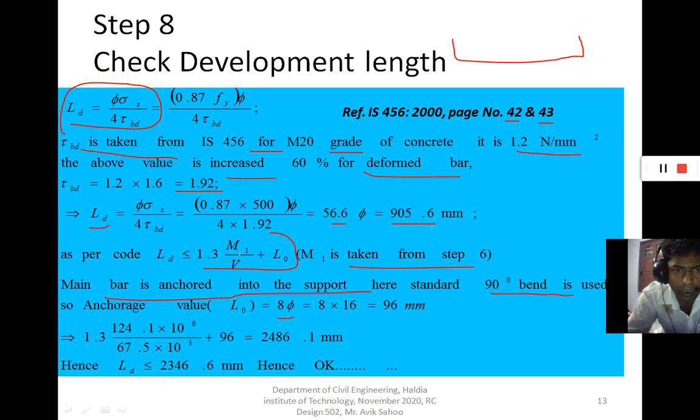And here the M1, approximately, because this value is very large, the big value comes, so to simplify the analysis, we consider it; this is actually the moment resistance that you have to calculate. So in a doubly reinforced section, it will take time, lengthy calculations are required.